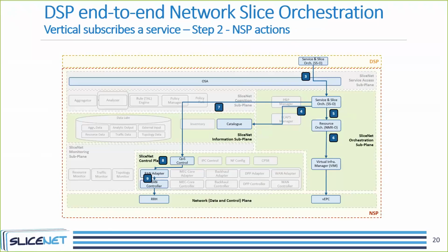This will be a mobile network slice, because it's not shown in the figure, but in our smart grid test bed, for the vertical, we have the IEDs, which are the equipments that communicate between each other to protect the grid. These equipments will use this mobile network slice that was deployed to communicate between each other, to open and close these relays. These IEDs are relays that open and close to protect the grid. We need low latency for that, so we need 5G to have very low latency for them to be able to close and to prevent the power grid failure from spreading among several customers, and to be confined to the minimum possible.